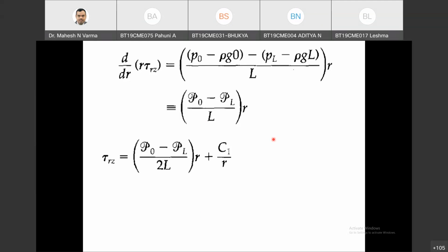Which pressure is it measuring? There are two pressures. One is the hydrostatic pressure, just because of the liquid head there will be pressure, which is also called the potential head. The other is the pressure given by the pump in a pipe. So which pressure is measured by the pressure gauge? That is actually a combination of both.